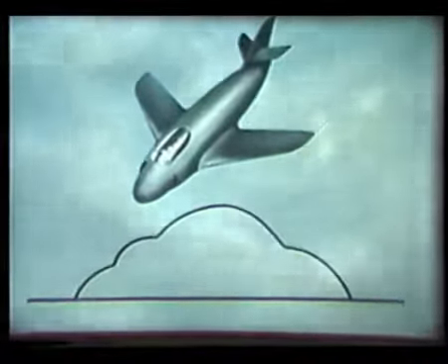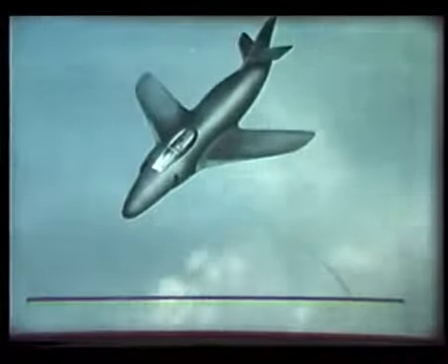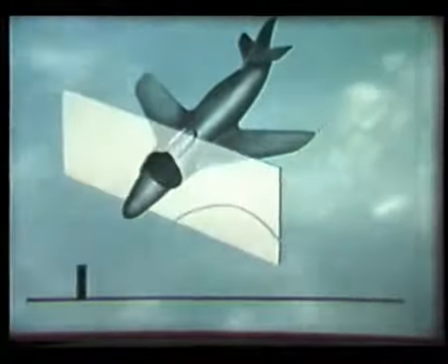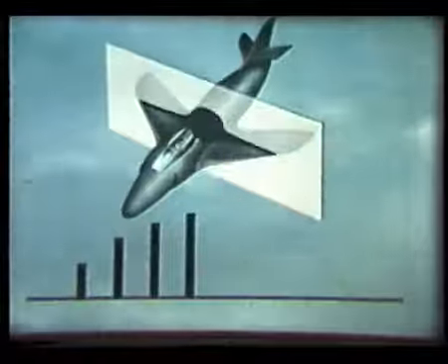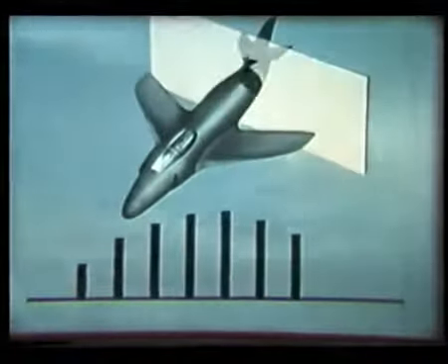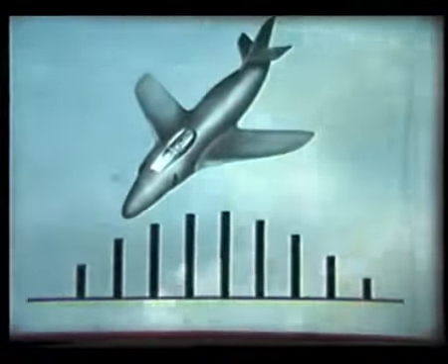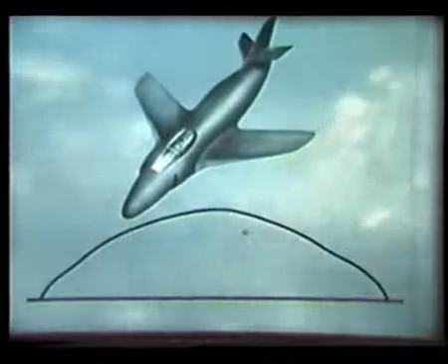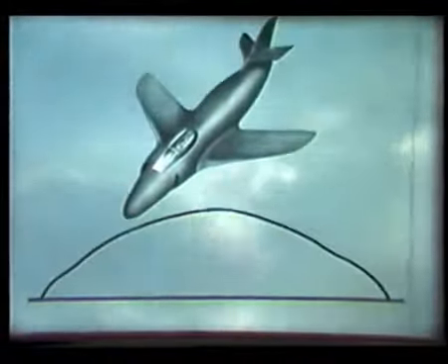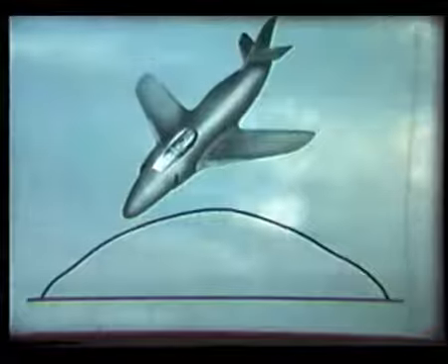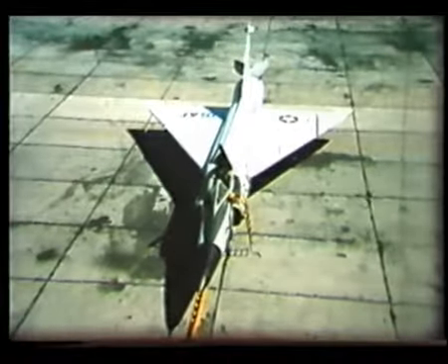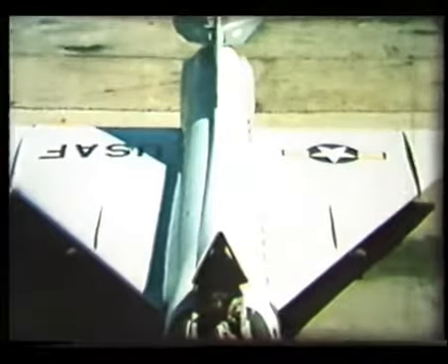Let us redesign the aircraft to smooth out the bumps in the curve so that the cross-section area changes gradually and not abruptly. So instead of the curve with bumps, a much smoother curve is obtained. This means the fuselage must have a waist to compensate for the wings and must flare out again behind.